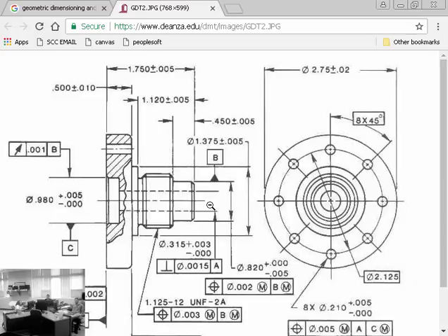That's normal. It's okay. The trick to dealing with these dimensions is just to isolate what you can. First of all, I start with the letter A. I see it down here and I'm establishing, okay, this makes sense. Look what we're doing. We are using the back side of this part as a datum. Agreed? Does that make sense? And while we're at it, we're going to throw a tolerance on it of, what type of tolerance is that?